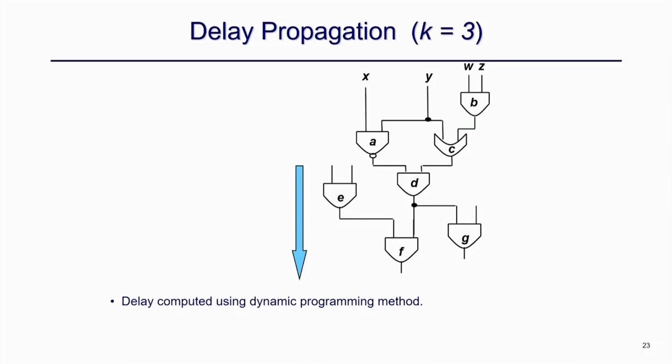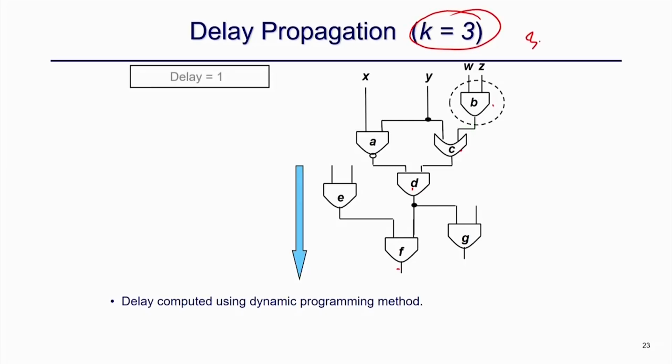So, before that, how to calculate the delay, what is the LUT delay. In this circuit you can see there is a path from here to here. This is the maximum longest path, and 1, 2, 3, 4, so 4 units of logic delay, right. That is the logic gate delay in the normal RTL circuit, but if you map this into LUTs, what is the delay, right. This is something we are going to understand. Suppose my target is a 3 input LUT, right.